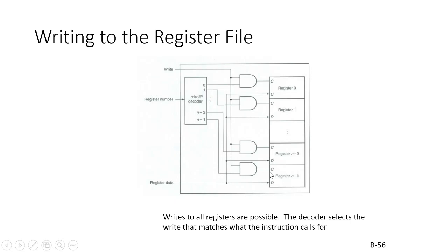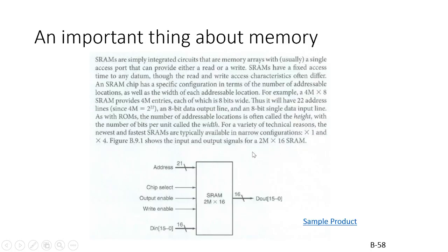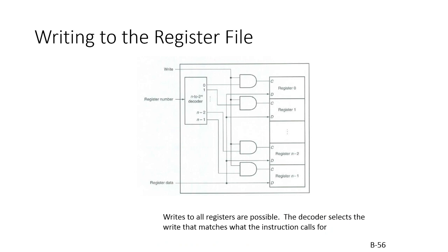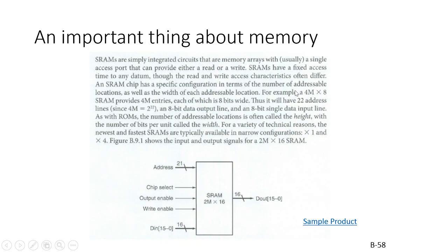So you can see though the register data goes to the D of each flip-flop. These are just the flip-flops I introduced here from the book a second ago, right? The write comes in on the clock cycle, right? That's enabled, and the value comes in on the register data. Okay, well, again, this all kind of bootstraps. You can take one of these, put these together in an array, and now you're building RAM, right?